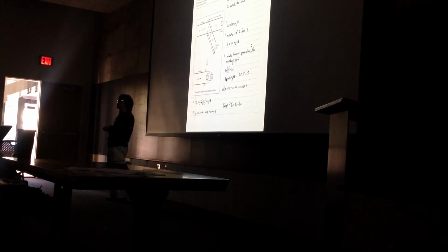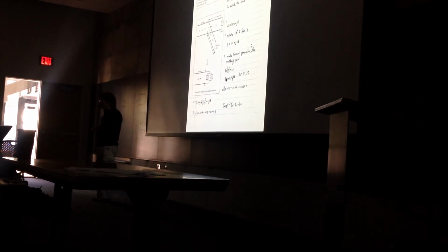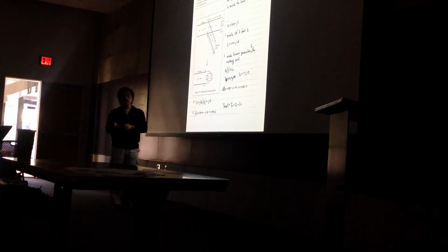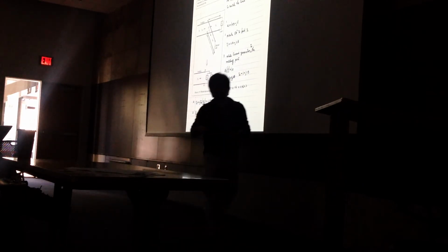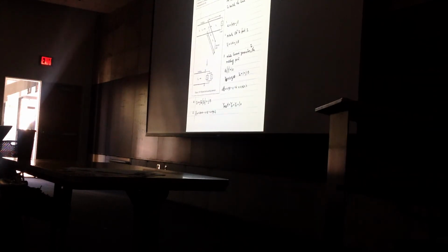So in a straightforward way, you will say, why don't I just simply go to Radio Shack and buy an inductor at a frequency such that 1 over omega L is equal to 1.5. So you can find out what inductor you need and then connect to that. Okay? In microwave, we don't like the lumped circuit. So we want to do it using the transmission line itself. Okay? And this will also provide a wider band kind of matching.